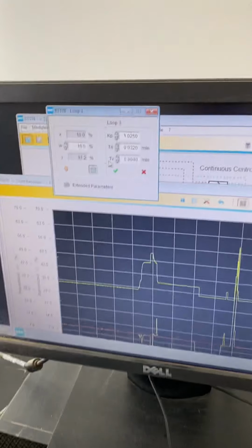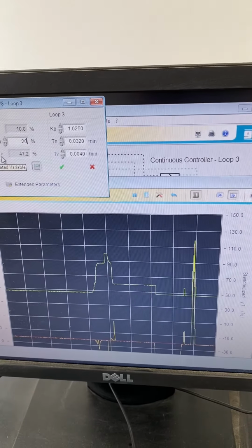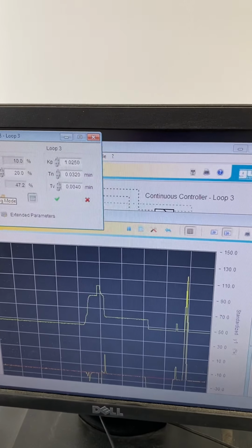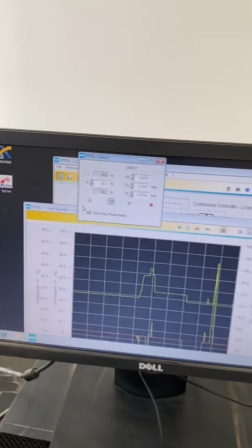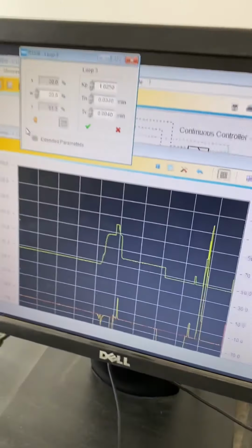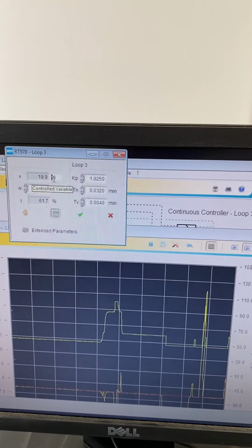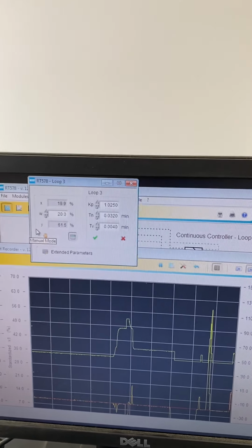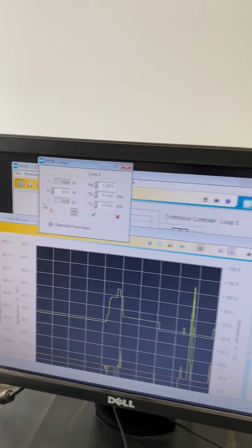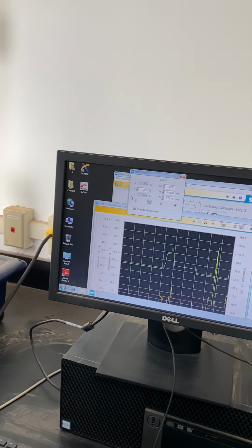Let's go to 20% set point. Okay. And I'm doing this to show you the relationship between the process value or the flow rate and the discharge pressure of the pump. And we will see that they are inversely proportional. The relationship between them is an inverse relationship.